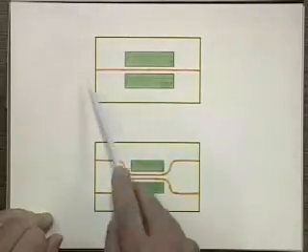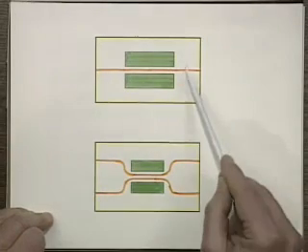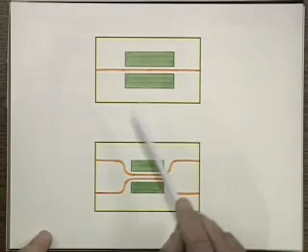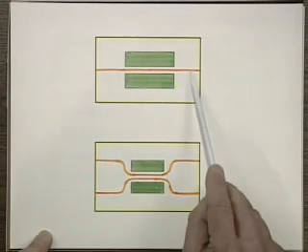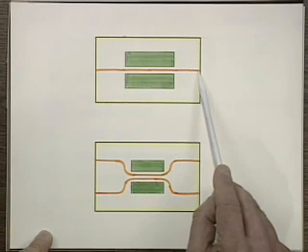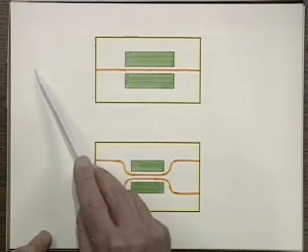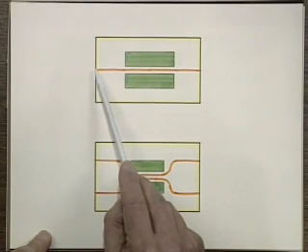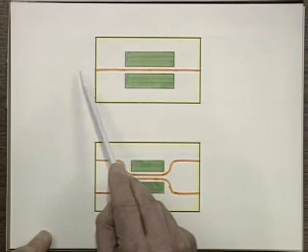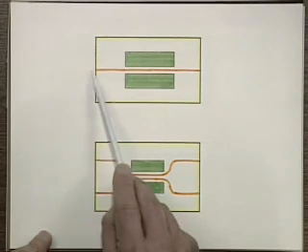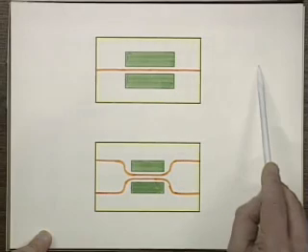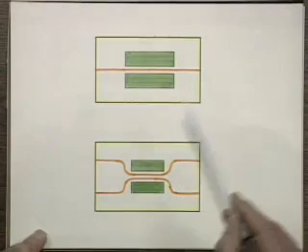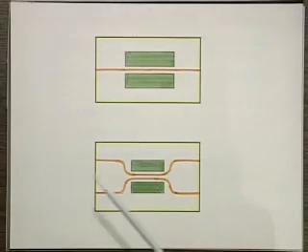Here again is the substrate, and here's the waveguide. Before I get to what I want to talk about, you have to first couple light to this waveguide. Remember, the core can be very small, just a few microns. So you have to take the output from the fiber and couple it into this core. That's a tricky device, but again, people have found nice techniques to do that. Basically, you want a fiber to couple into this and this to couple into the fiber going out. If you can do that and these couplers stay together, then you've got something.